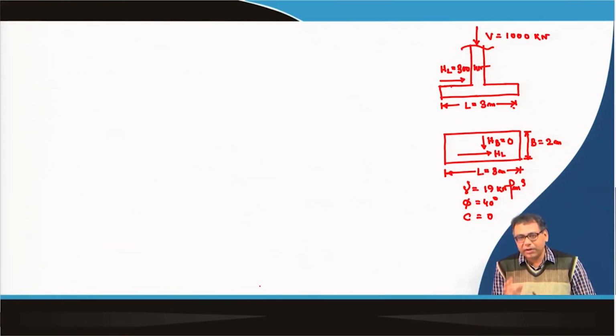So if a triaxial phi value is given and you want to use it under plane strain condition, or in other words where the length of the foundation is higher than the width of the foundation, then we have to modify the phi value.